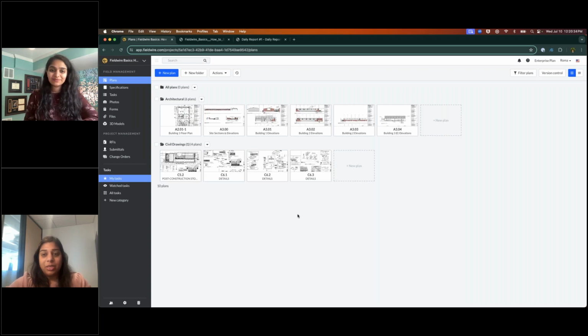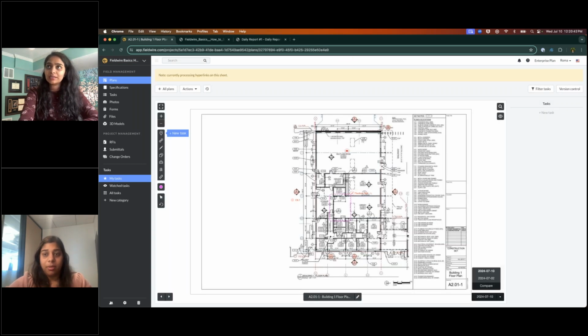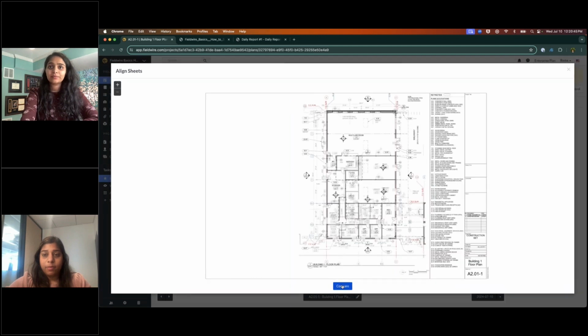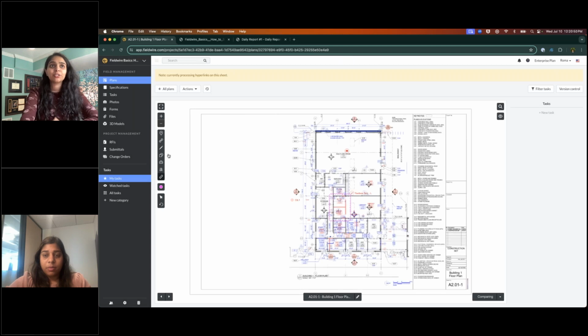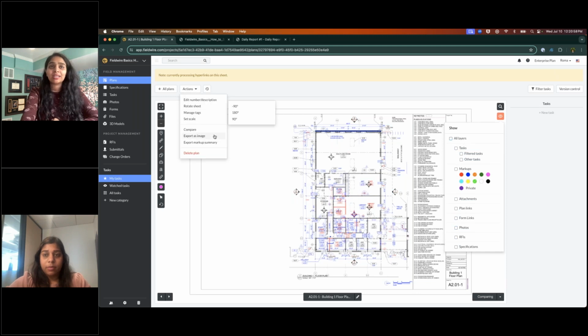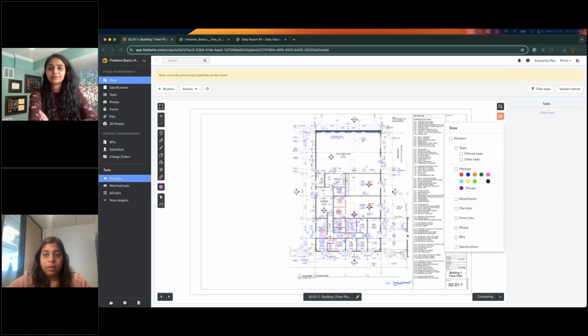And the next question is, can you export the overlapping prints? Like once you overlay two prints, is there a way you can export them? So let me hit compare. And I'm glad you asked this question. If I don't want to show my overlap, there's my eye. I can turn this off and then export as image, and this will bring up an export of my compare. Oh, it opened on my other screen. Give me a second, but here it is.